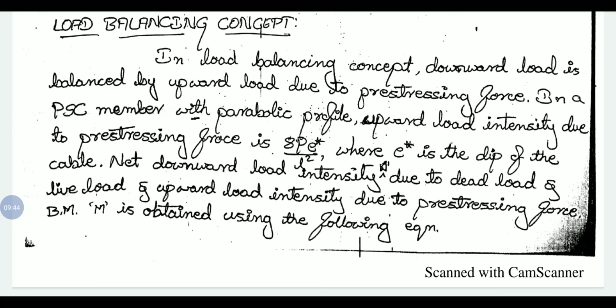By using this concept, we are going to design the section for the extra amount of 50 kilonewtons, that is, 100 kilonewtons of prestressing force is balancing 100 kilonewtons of dead load and live load. The additional 50 kilonewtons will be considered for the design of the prestressing member. So for that,